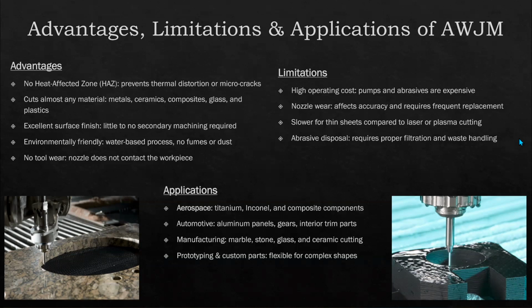The equipment itself is expensive and it requires a lot of maintenance, especially since the nozzle wears down from the abrasives. It's also not the fastest option for thinner materials, and the used abrasive material has to be filtered and disposed of properly for environmental purposes.